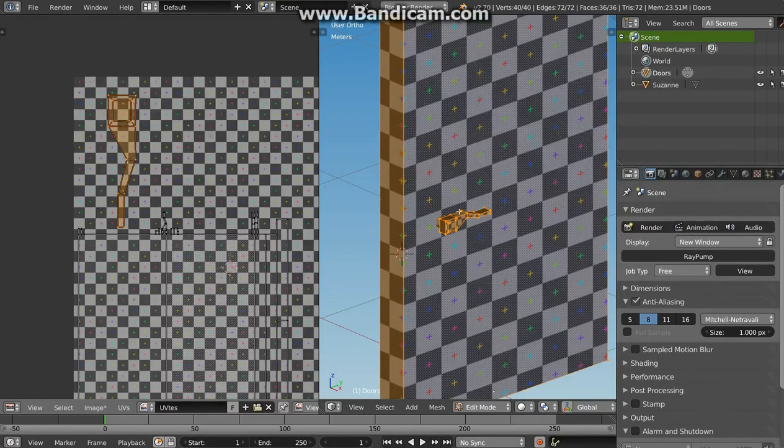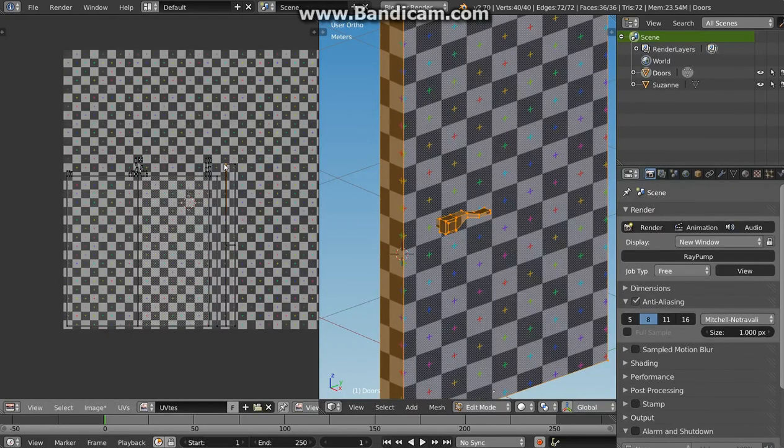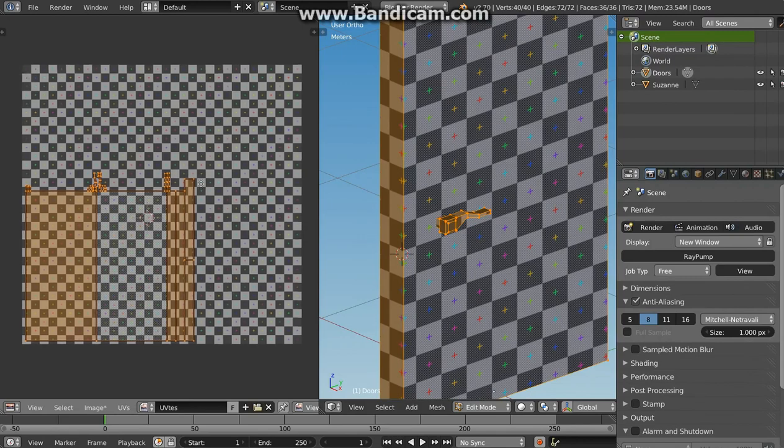For everything you do, never scale only one island from your UV coordinates. Every time you see that you can place more things there, never try to use the UV coordinates to fill the space.